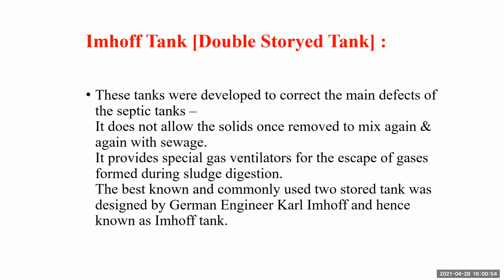So what are the defects that are corrected here? It does not allow the solids once removed to mix again with the incoming sewage. What happens in a septic tank? There is a single chamber, so when sewage comes in through the inlet, the solids that have settled down get mixed up again with the sewage. This does not happen in the Imhoff tank.